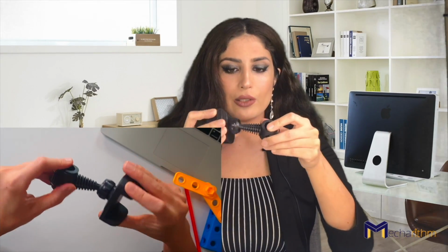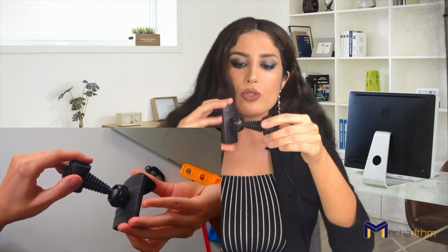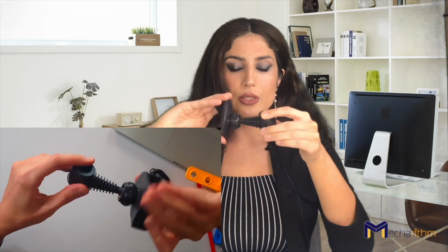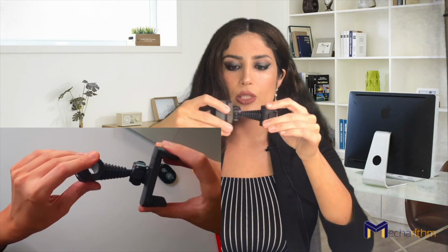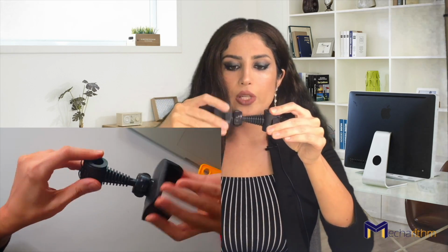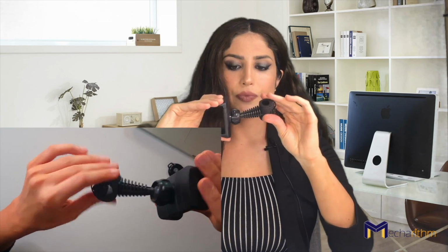The spherical joint, which we also call the shoulder joint or ball and socket joint, is the same as the universal joint, but it also has another degree of freedom, the rotation around its axis. So it has the 2 degrees of freedom of the universal joint plus the rotation around the axis of the joint. Next is the cylindrical joint that can provide independent translation and rotation around a single fixed joint axis. So it can provide us with 2 degrees of freedom.